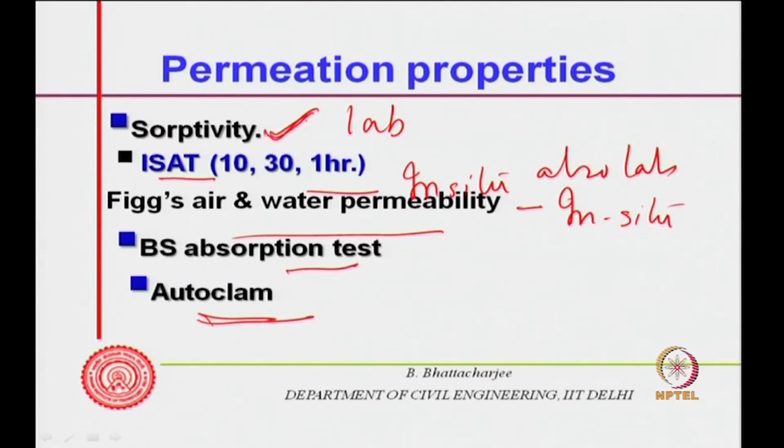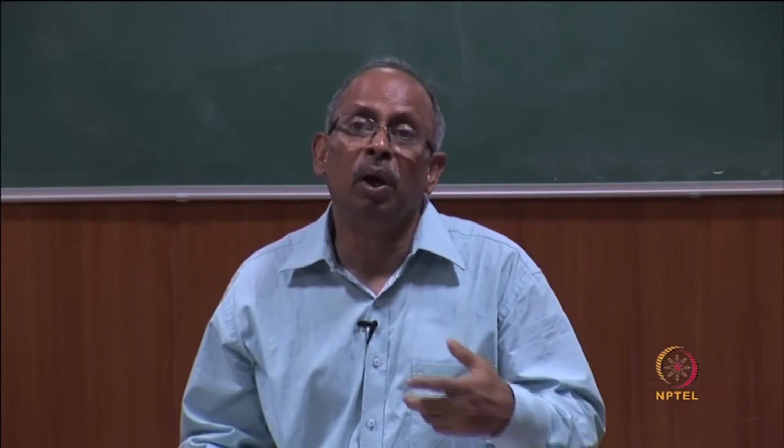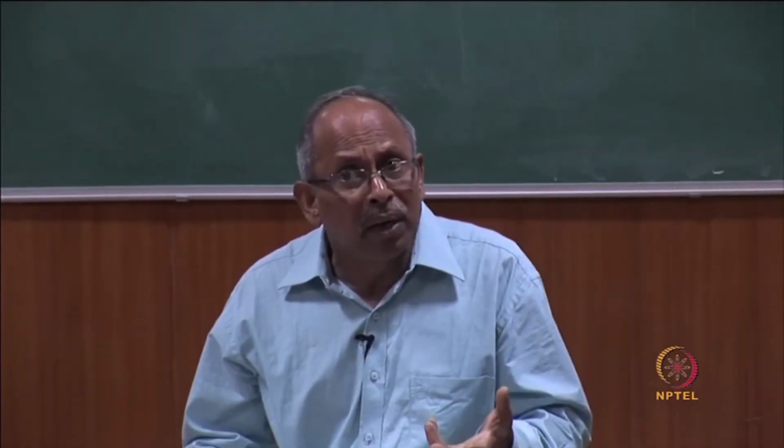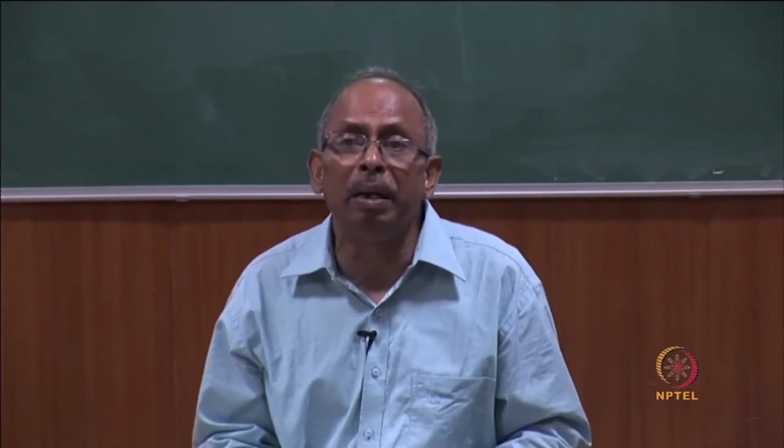So, there are several other properties. There is one in Switzerland, some modification of this one, because this requires vacuum application. So, without the vacuum application, there are several of them which are there, and some of them can be used in situ, not on the lab specimen, so that you can find out the durability performance of concrete in structure. Permeability is difficult to determine, but these ones will be relatively easier.